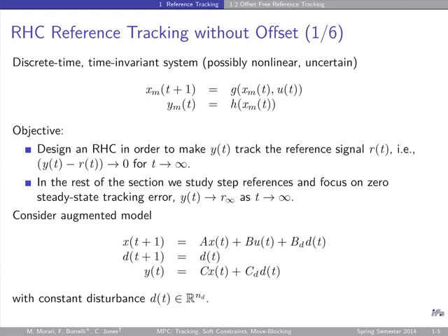In industry, and for many practical applications, it's very important to have no tracking error, even if your model may be changing or inaccurate. This is a very important feature of most MPC controllers that you would implement. And with some minor assumptions, all those stability considerations, the invariant sets, target regions, etc., carry over to this MPC controller and this general formulation.